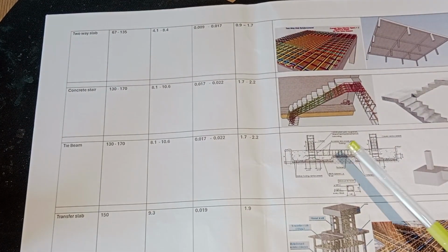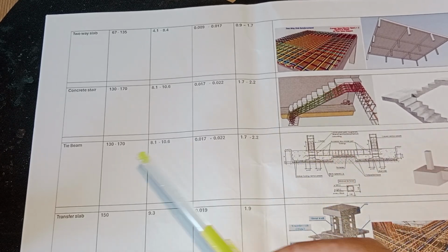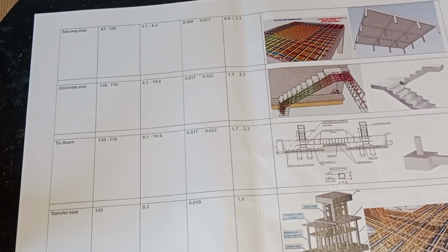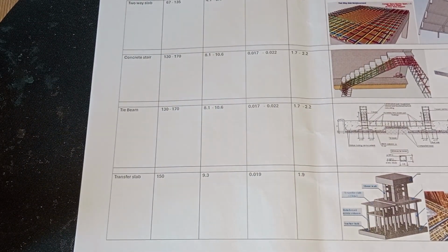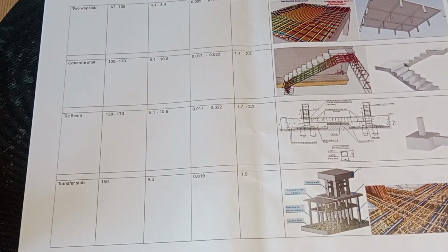Here it is, the type of floor beams, and in this case we have about 130 to 170 kilograms and 1.7 to 2.2%. You see here that's the long reinforcement we have, and we have many stirrups mainly in the middle to avoid any shear problem. That's generally a minimum. There's no big load in general, and if you just follow the minimum reinforcement in the code, it is good design.